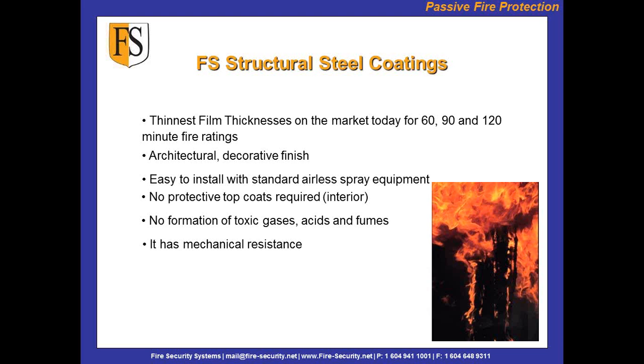So on top of that, like we also discussed, there are no protective top coats required for interior use. In its wet, dry, or under-fire stage, there are no toxic gases, acids, or fumes. That's for both solvent and water-based? Yeah, everyone thinks that because it carries solvents, when it burns there's going to be an off-gas or acids or fumes. Actually, solvent-based coatings carry solvent in their wet form only. Once fully cured, it carries no solvent.